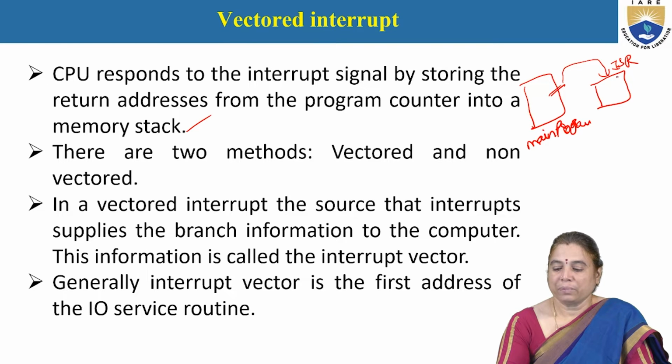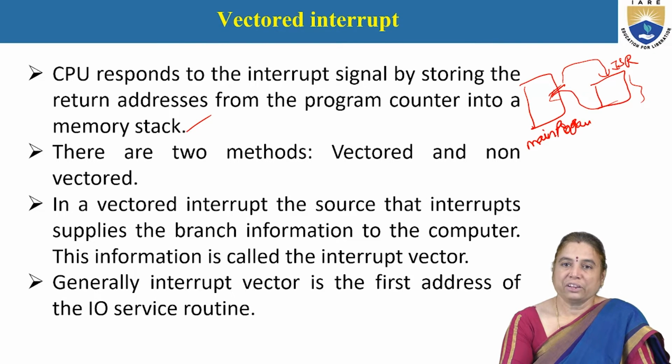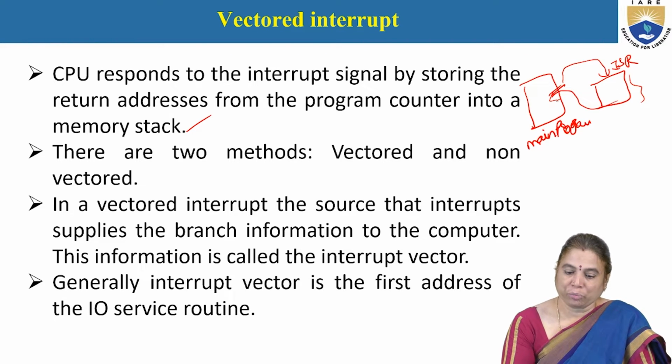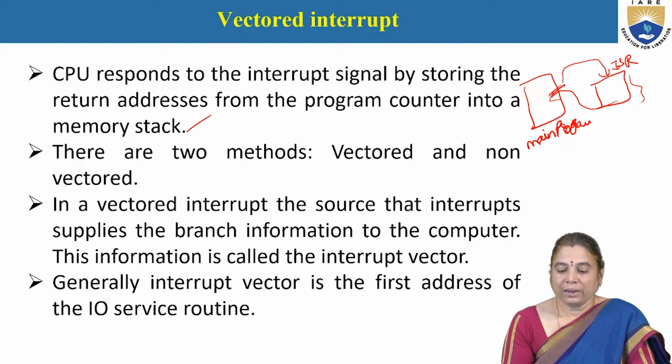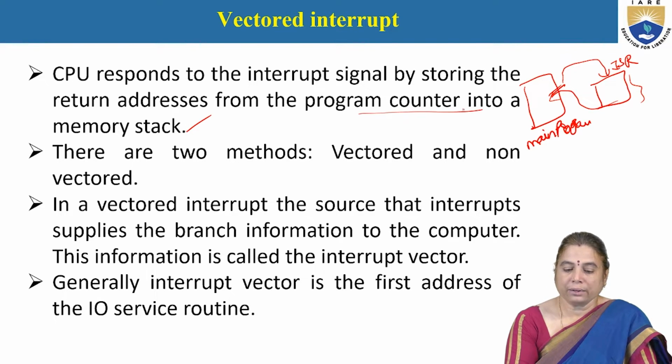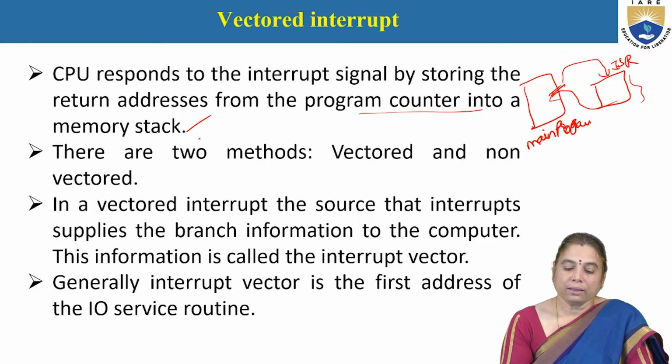So as soon as the input-output operation completes, it must return to the main program and resume its execution. Before control transfers from the main program to the interrupt service routine, the return address is pushed to the stack, so that when the IO operation completes, popping the return address from the stack pointer lets the main program resume. So there is a need to store the program counter address in a memory stack to service the interrupt.